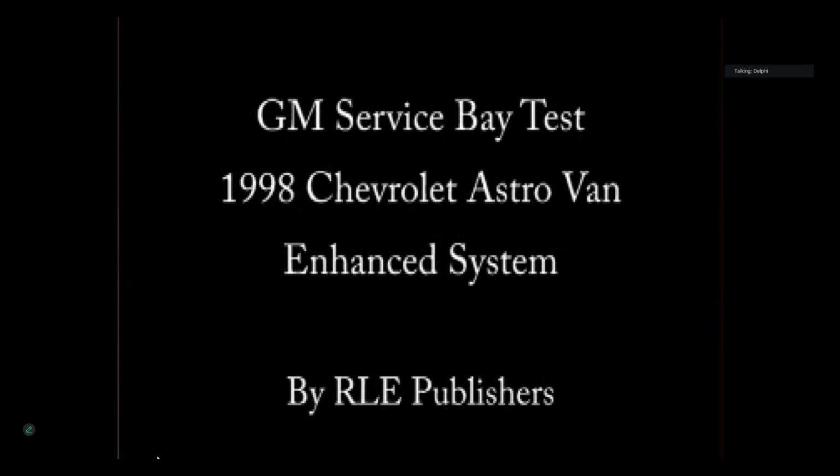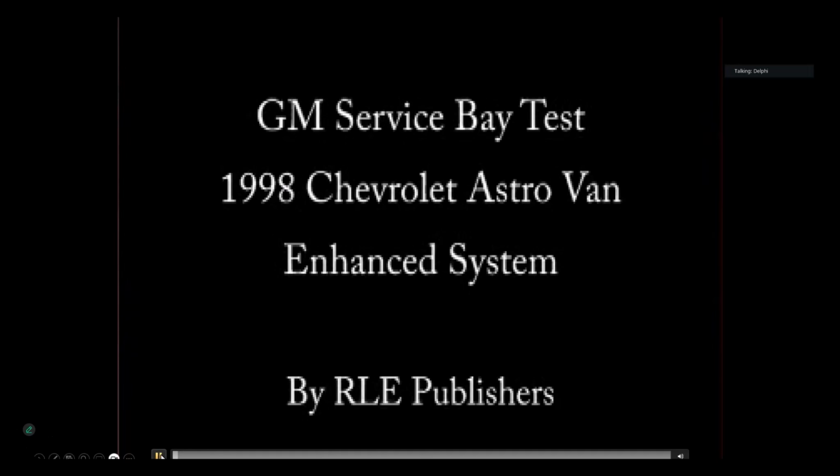Now when you run a service bay test, we'll talk about this in the next class, but some of these won't set the flag. Some of them will set a DTC for this test, but they won't put it in memory because it was just a service bay test. And sometimes on these, we'll talk next class with Honda especially, where Honda and Ford, they run service bay tests, but in reality, you got to be careful. They don't run the small leak test in the bay. But this one is just a conventional purge and vent, and it's going to run the test. So watch this one here.